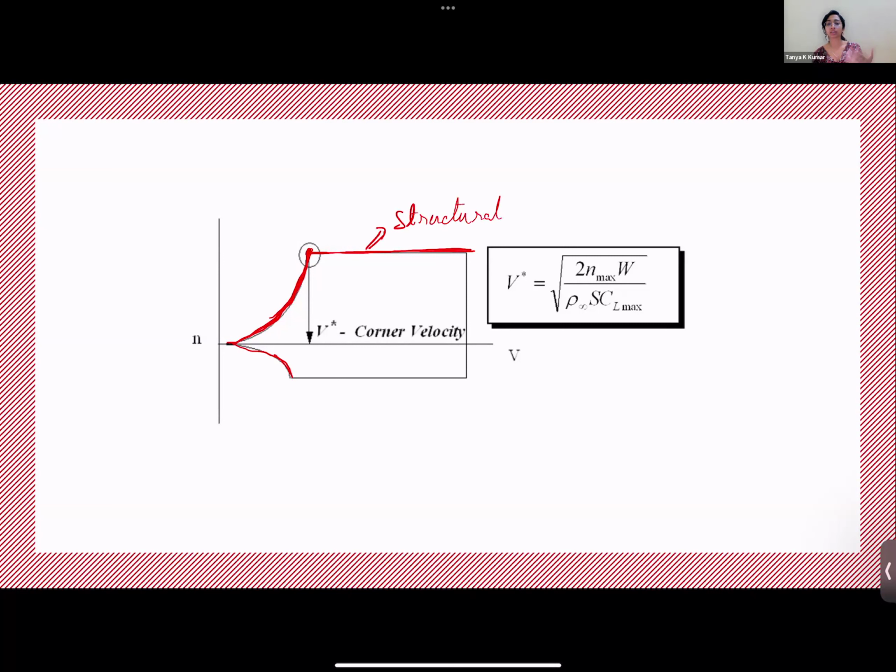right? So when you do your maximum G maneuvers, you encounter this N max, right? So max G maneuvers. What is this curved line? What limit is that? This is the maximum velocity that the aircraft can sustain because of the structural limits. What about the curved line? Max CL. So what is the velocity corresponding to max CL?